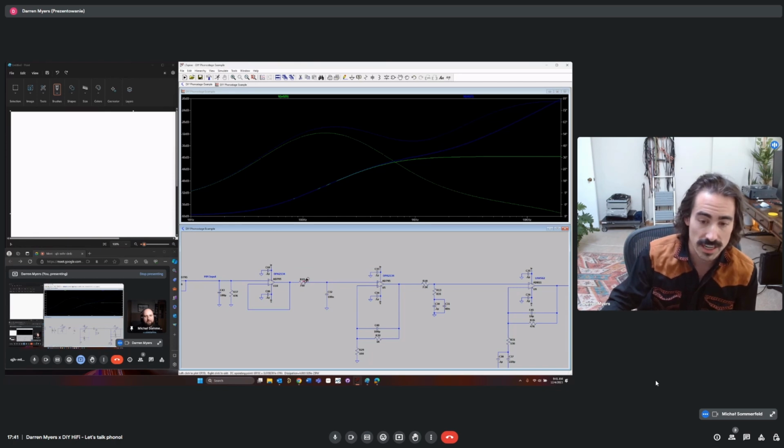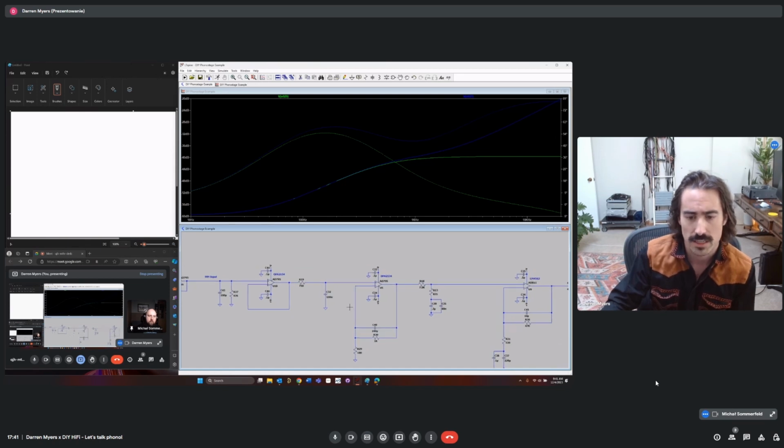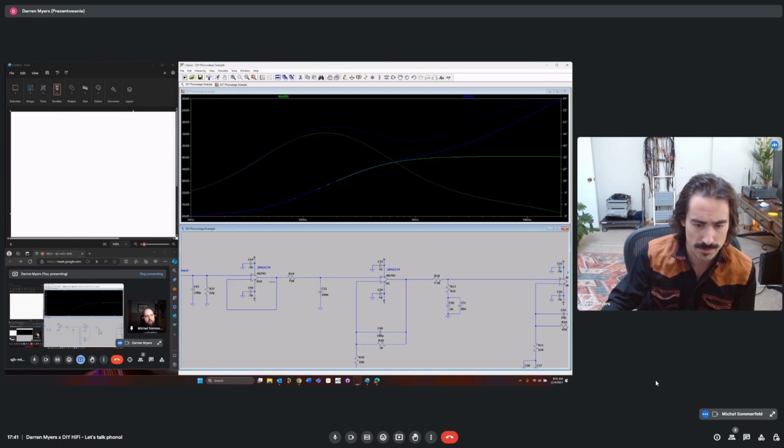And then R19 is being driven at high frequency by U10. So we don't want to use 75 ohms. So 750 seems like a logical kind of compromise. You could go down in value a little bit. You could cut that in half and then double C32 if you want. That would improve the noise performance, but make sure your U10 can drive that impedance at high frequency.